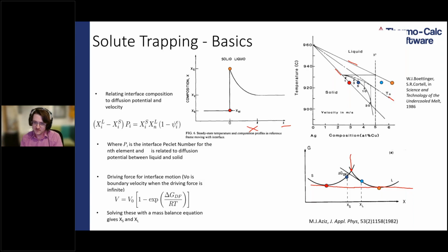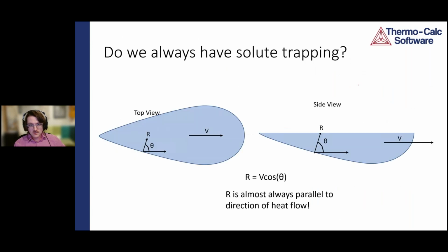Okay, so that's kind of the basics of what you need to know on how we can handle the rapid solidification that happens in these processes, and how we can take the thermodynamics that we've described at equilibrium and transform those thermodynamics to be able to account for the rapid solidification and hopefully accurately describe the rapid solidification. And it works pretty well. But I should say, you don't always have solute trapping.